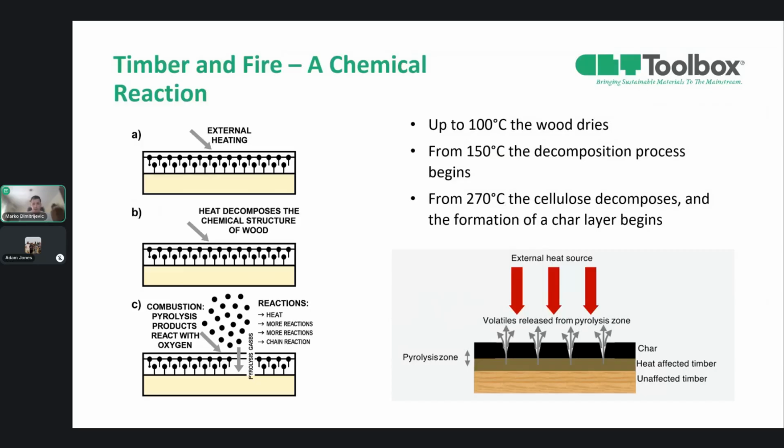So fire is a chain reaction between oxygen, fuel, and heat. It requires all three to be available. In most buildings, there is adequate oxygen, and it is the availability of fuel that dictates the initial growth of fire. Pyrolysis is the primary mechanism, where heat breaks down wood into combustible gases and char.